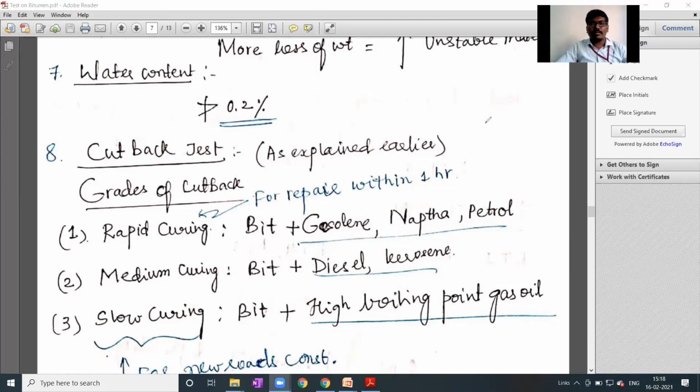That's why, whenever water comes on the pavement, the pavement is provided with some camber, right? Because the water should be easily drained off to the side drains. No water should be left on the bitumen surface. That should be taken care of, because the enemy for the bitumen is water itself. Okay, so I'll be moving to the next.